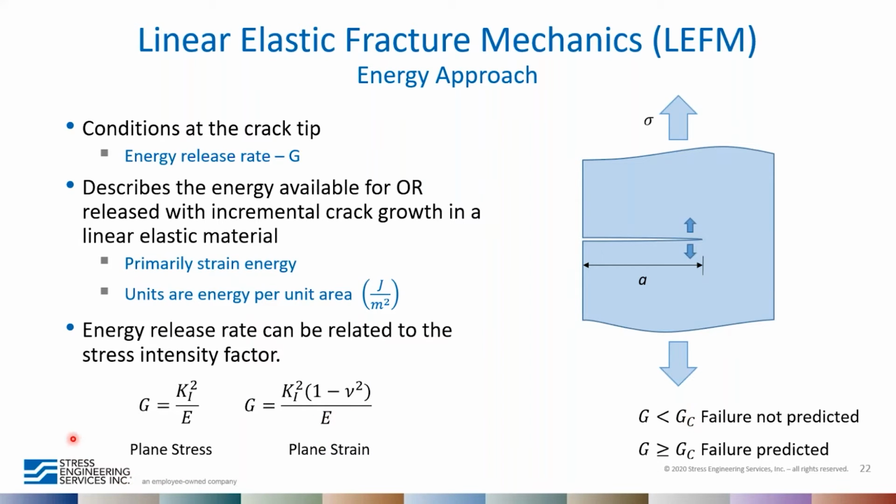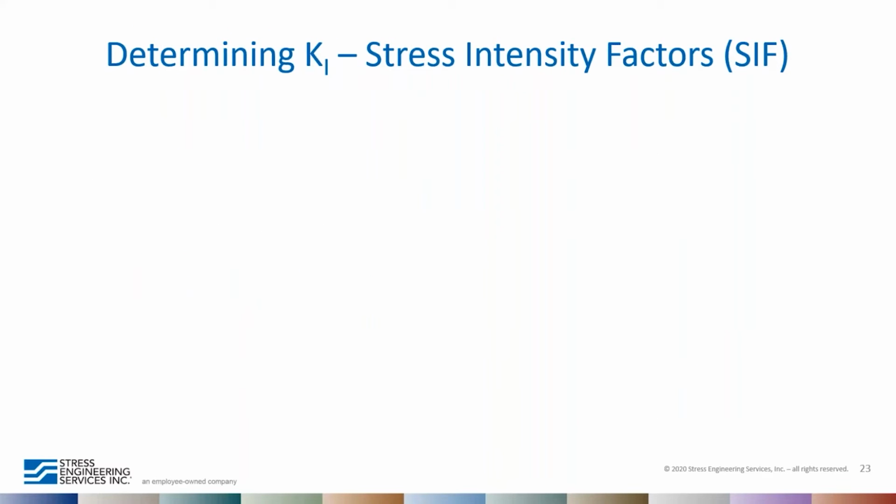Now, the energy release rate can be related to the stress intensity factor using this equation. There's a slight modification between plane stress and plane strain, but this really highlights the fact that the two terms describe a similar effect or similar mechanism in linear elastic fracture mechanics, and they are equivalent.